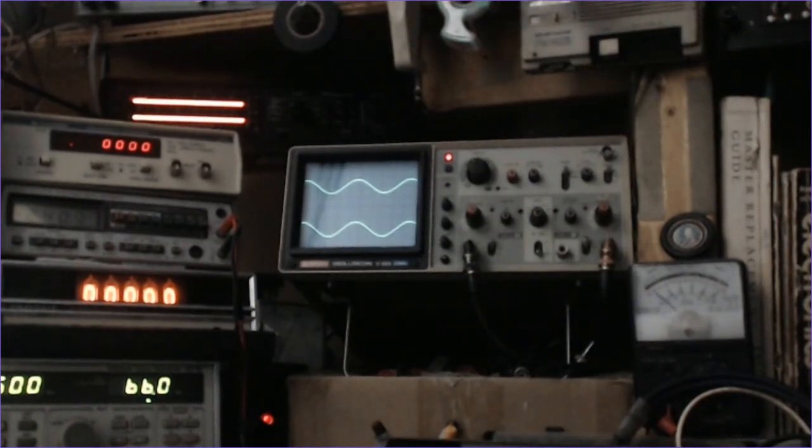Full power is achieved when the top and the bottom of the sine waves start to flatten out. That's called saturation. If we run it at that point very long, we will destroy output transistors because the current draw is much higher than it's designed to. So I'm just rocking this back and forth. It also sounds extremely distorted. So we can drive both channels to full power.